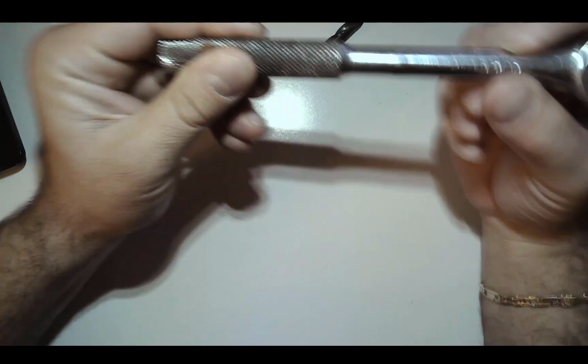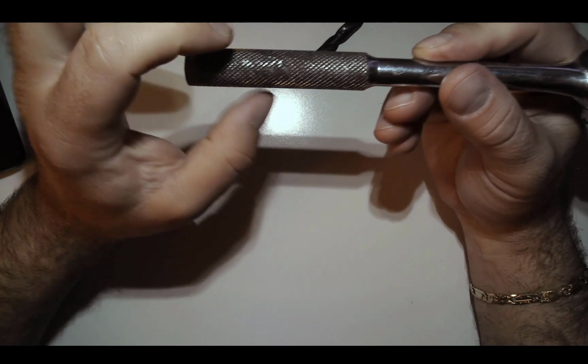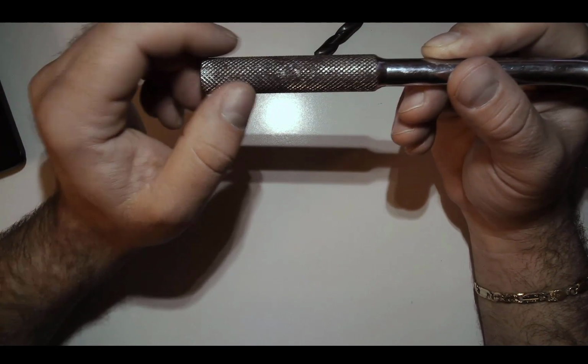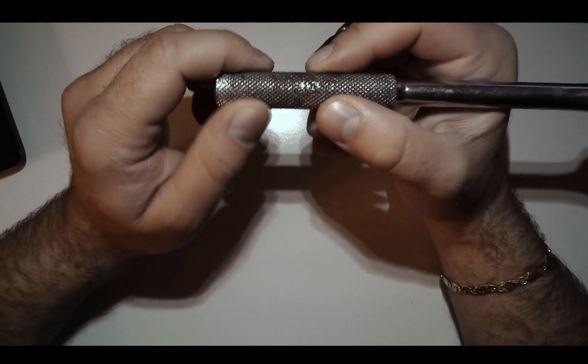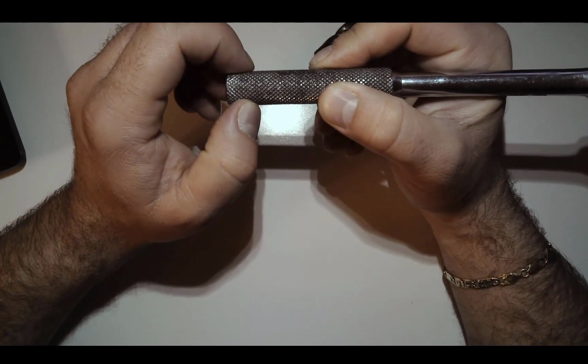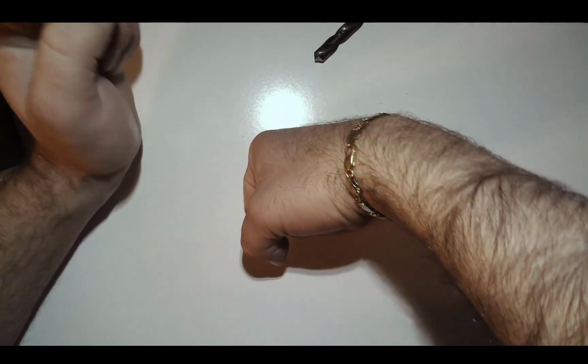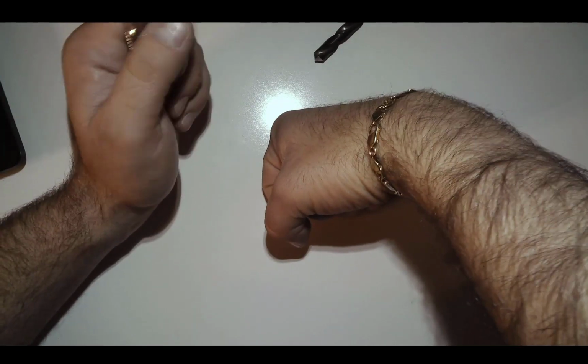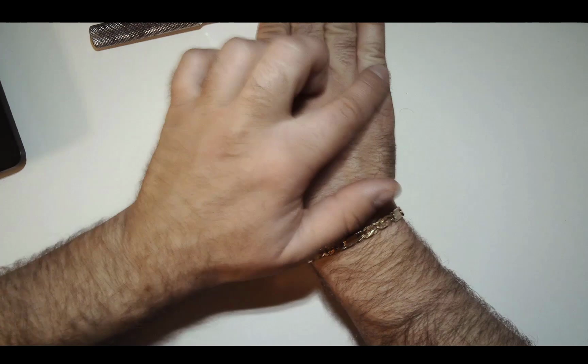This thing will turn on the lathe, and there's two wheels that have the opposing angled pattern, and what happens is it just is forced into the surface, and it's like if you took your hand and pushed it into some Play-Doh on the table, you would have peaks and valleys. So wherever my fingers touch the Play-Doh, I'd have peaks and valleys that would fit between my fingers, because the dough has to go somewhere. Well, the metal has to go somewhere.